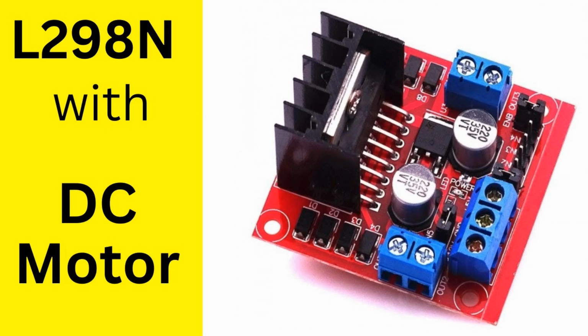Disadvantages: more computationally intensive and requires advanced algorithms and processing power. It also increases the cost and complexity of the driver. Applications: common in high-performance systems where smooth control is essential, such as in electric vehicles, EVs, drones, robotics, industrial automation, and other precision motion control systems. Examples: VESC, for electric skateboards and drones, O-Drive, for robotics and electric vehicles, ST Microelectronics Spin Series.